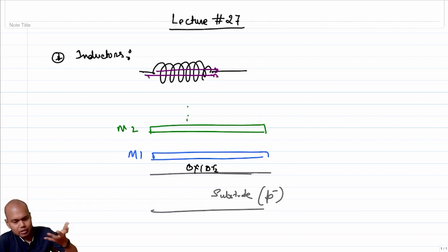And as it turns out, these vias are not very efficient in terms of the unit resistance that they provide. So the most effective way of designing an inductor is essentially to draw circles on a planar topology, right?